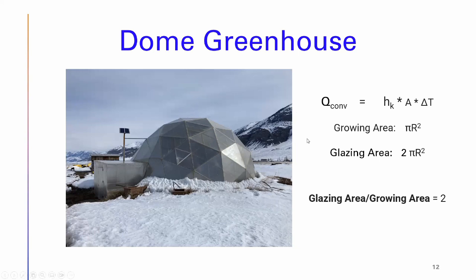I can't remember off the top of my head what it is per inch, but it's maybe half of what polyiso is. Blue boards, I think, are about R5 per inch. So there are different options, but what I'm recommending is, after you've built your greenhouse and oriented it east to west, glue in or otherwise mechanically fasten rigid insulation to your north side.